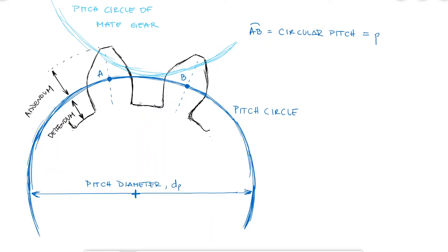Remember when you talked about the radius of a gear when working on simple angular velocity and torque topics in physics? Or the radius of a gear in a simple gear setup during your mechanics of materials torsion examples? What radius were you using then? Was it the distance from the center to the base of the gear? From the center to the top of the teeth? Even if you didn't know it then, it was a radius equivalent to the pitch diameter divided by 2, or